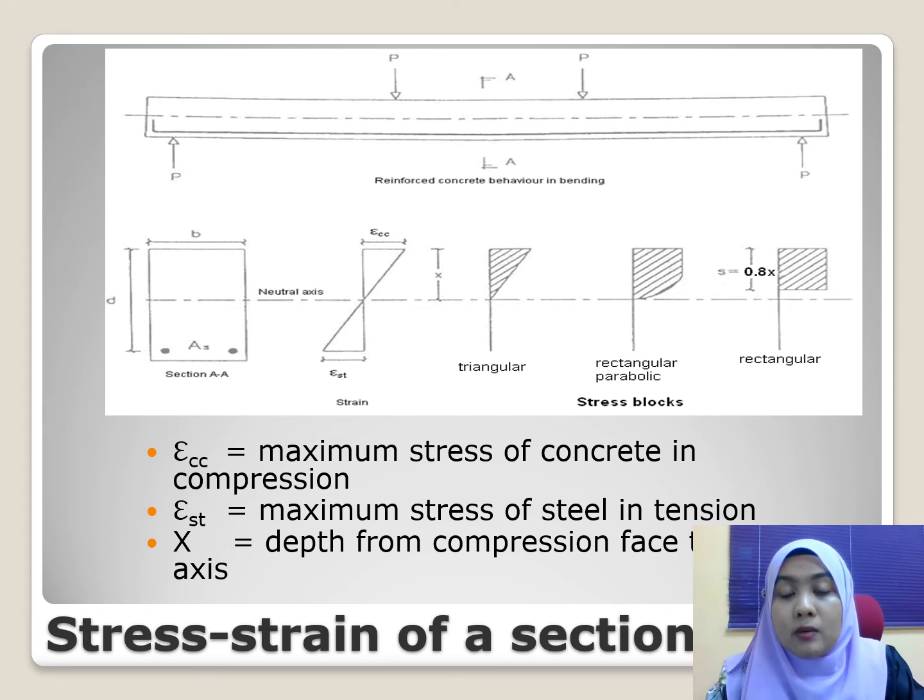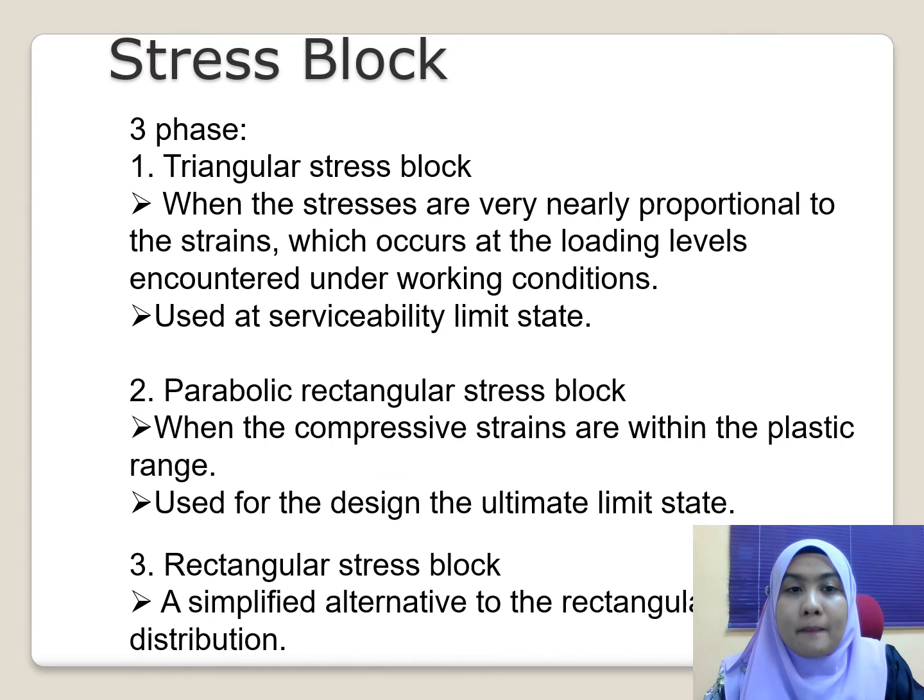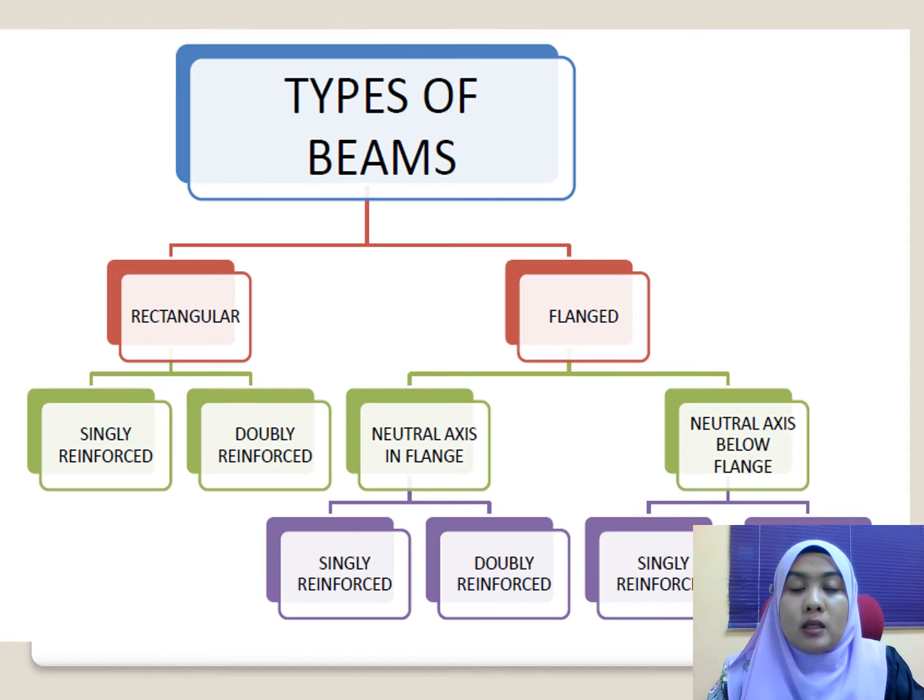To simplify this rectangular parabolic stress block for design, we simplify it into a rectangular stress block. We are going to use this stress block to derive the design formula. So these are the three phases of the stress block: the triangular stress block, the parabolic-rectangular, and the simplified one.